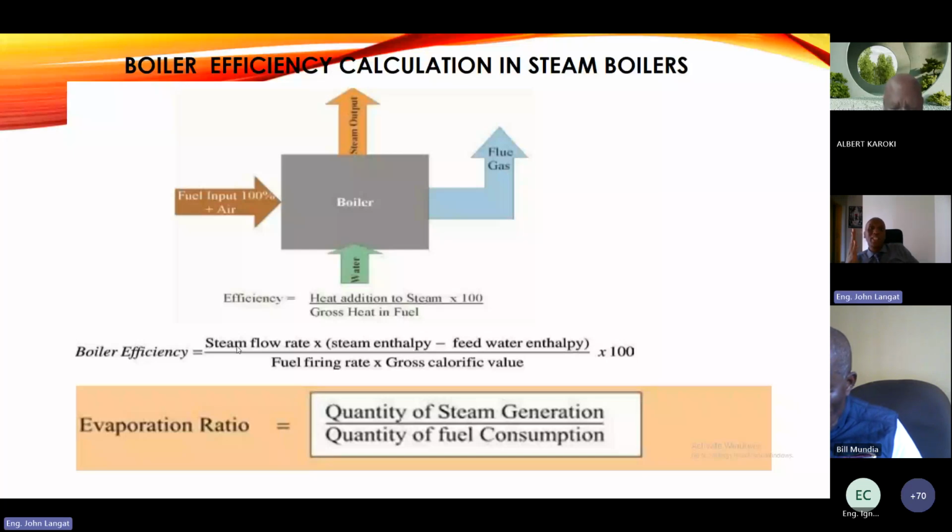For the reason that steam at 10 bar and condensate at 4 bar do not have the same specific volume. So you'll not get the same flow rate. So if you find an establishment recording those ones, they are lying to themselves.